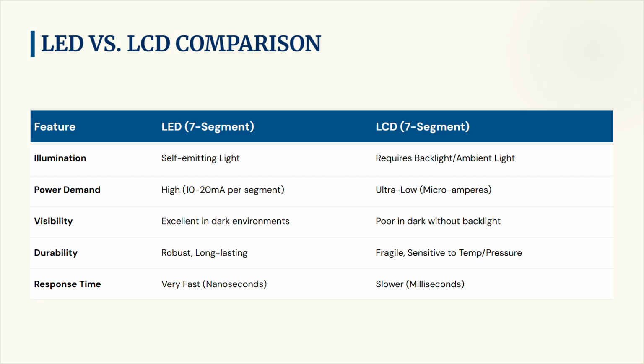So liquid crystals naturally align in what I can say in layman terms, a twisted spiral. Light passes through these crystals. Crystals guide the light and twist it by 90 degrees. So it passes through the second polarizer. And when an electric voltage is applied, the liquid crystal molecules straighten out, they untwist. And in the straightened state, they cannot twist the light the way they were doing before. So the light hits the second polarizer at an angle such that it is blocked, creating a dark area, which you see as a pixel in LCD screens.